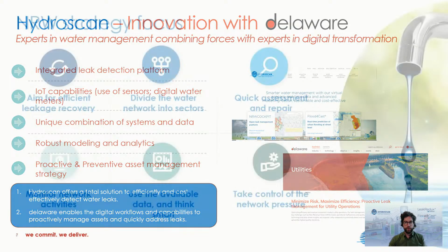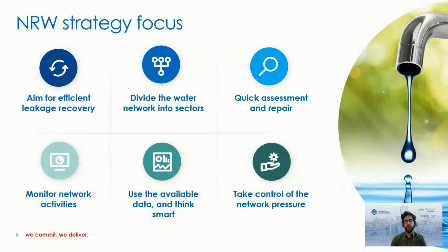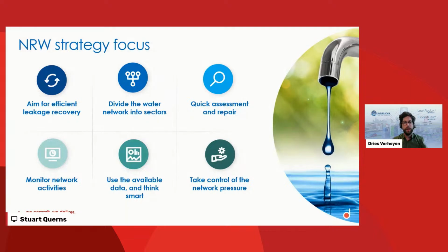And for the focus on NRW, what does the client need to do to manage their NRW well, or to diminish their water leaks? Most of the time, clients will divide their water network into sectors because it's more manageable, and they can track the leakage in smaller zones.